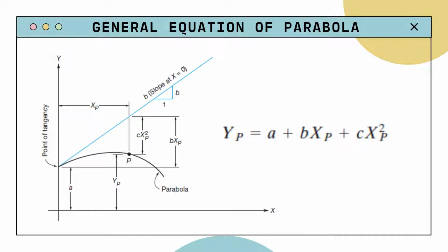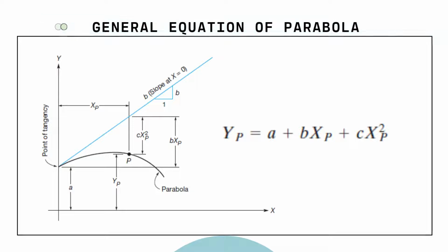Since a vertical curve is parabolic, we will be using the general equation of the parabola, which is y equals ax squared plus bx plus c, turning it to y sub p equals a x sub p squared plus b x sub p plus c in relation to the parabola. Parabolic functions have been found suitable for this case because they provide a constant rate of change of slope and imply equal curve tangents.